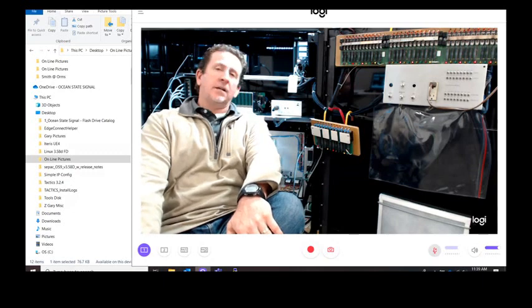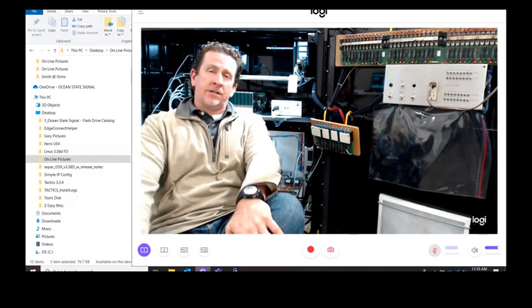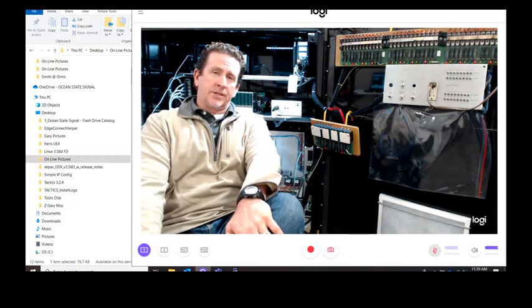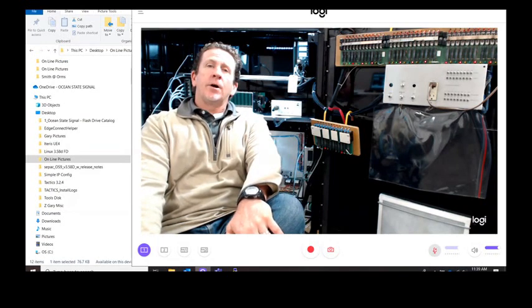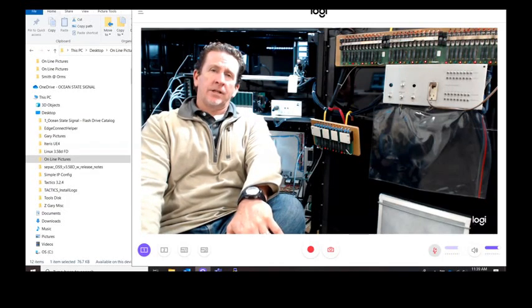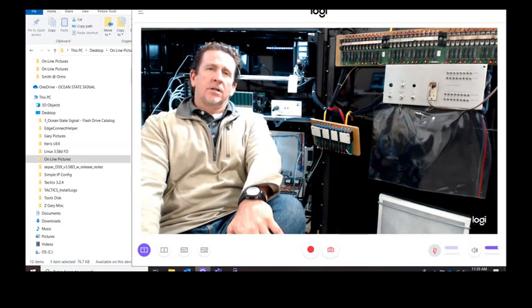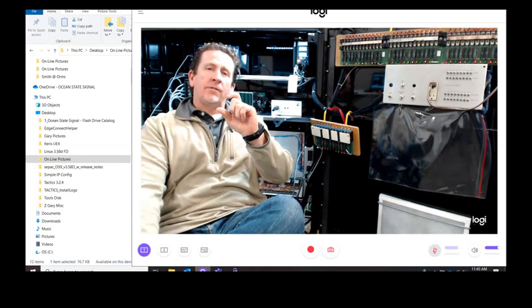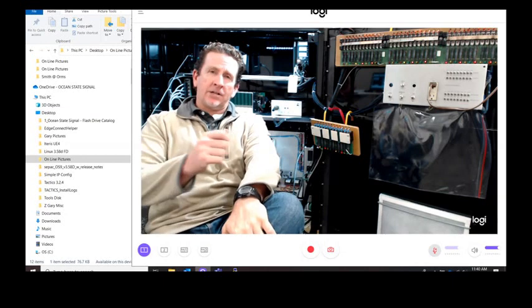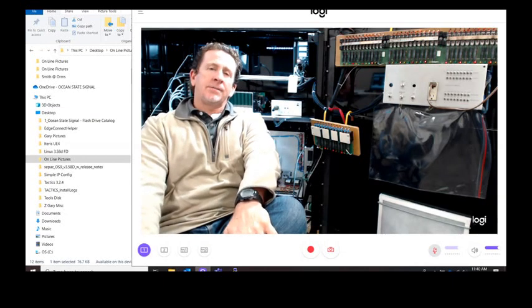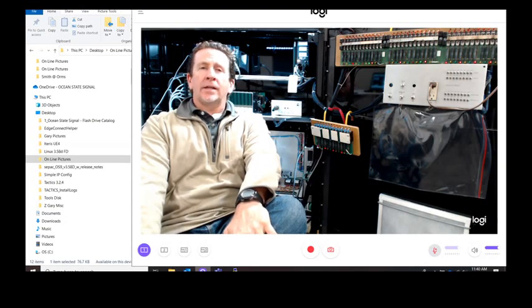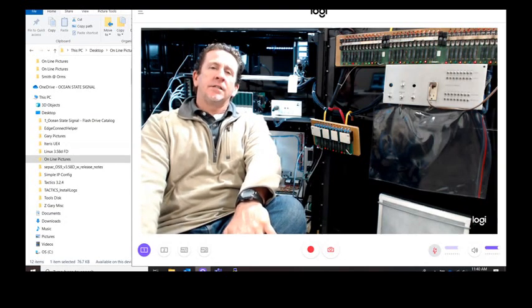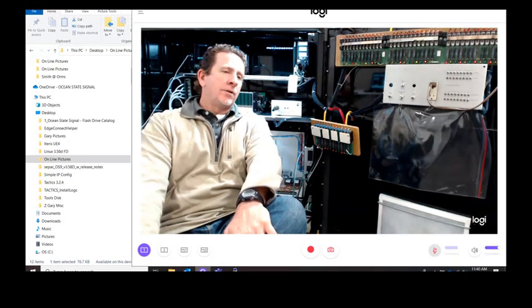Other places we've seen it cause that problem: you can have a bad flash transfer relay. Typically they don't go bad. You stick one in there, you get 25, 30 years out of it. But because that ties to your yellow flash circuit, a bad flash transfer relay can cause that same problem. And there's the yellow jumper wire that ties down on your field level wires for when we do our flash for red, yellow, no flash. I've seen instances where a problem with that yellow wire has mimicked a yellow clearance fail. But 99 times out of 100, you're going to have a bad yellow LED out there. We've all played with yellow LEDs.